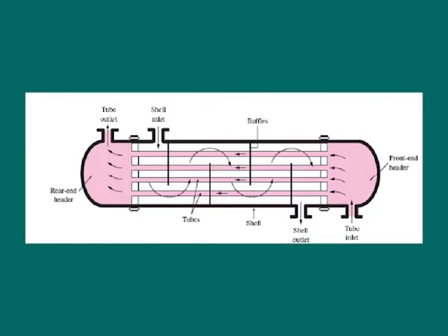They can be designed for special operating conditions: vibrations, heavy fouling, highly viscous fluids, erosion, corrosion, toxicity, radioactivity, multi-component mixtures, and so on. They are the most versatile exchangers, made from a variety of metals and non-metal materials. In Figure 2, additional tube configurations are shown, which are used in shell and tube exchangers.